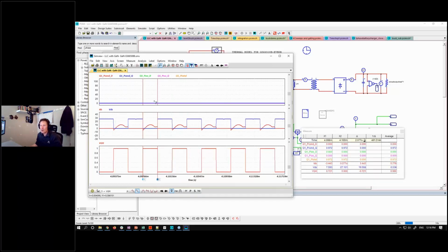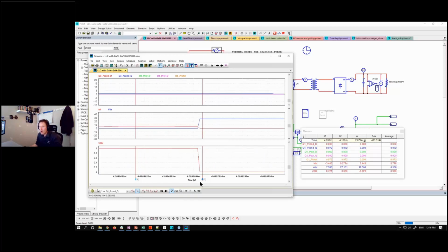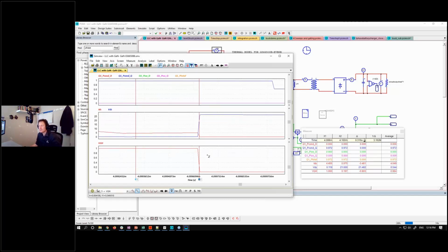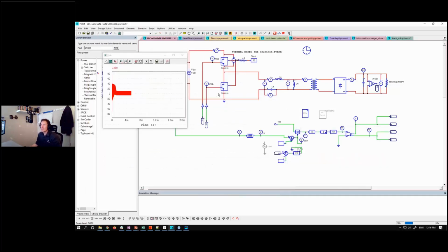Here we're turning off. We've turned off right here. And again, we're not seeing any switching losses because the voltage across it is off when it is switching. So our thermal model is capable of simulating the results of zero voltage switching and zero current switching on the losses. There are other webinars that talk about thermals and tutorial videos and all that kind of thing.